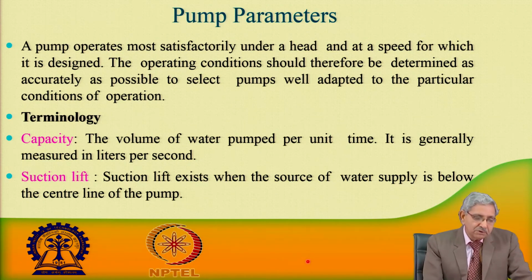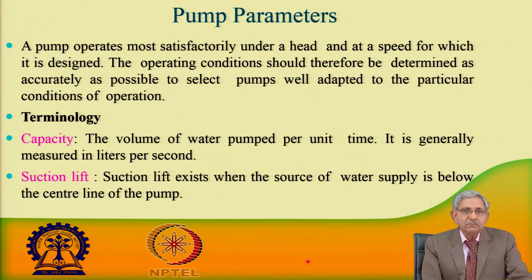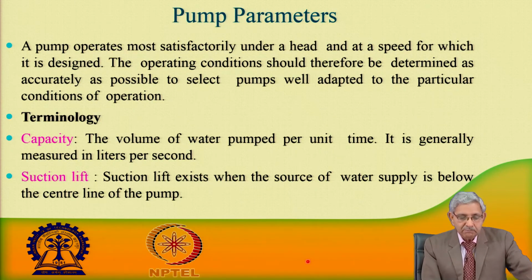These terminologies are capacity of the pump and suction lift. Capacity refers to the total volume of water pumped per unit time. It is generally expressed in liters per second. Suction lift exists when the source of water supply is below the center line of the pump.